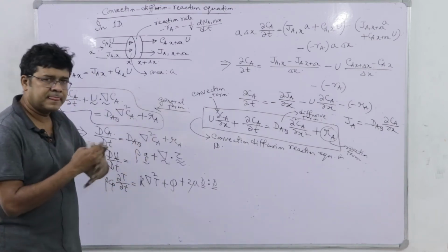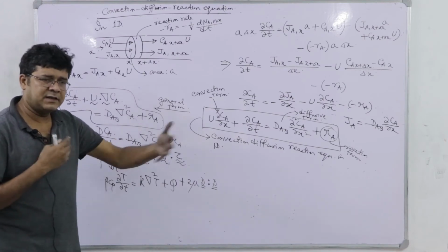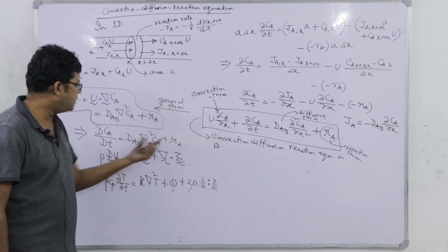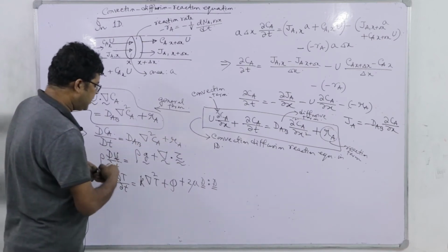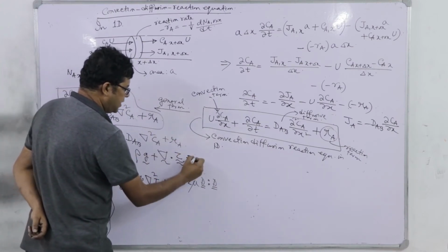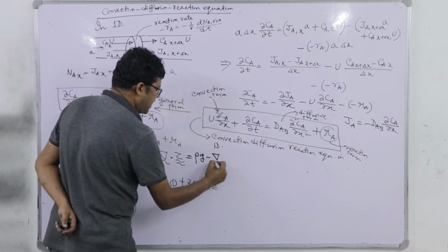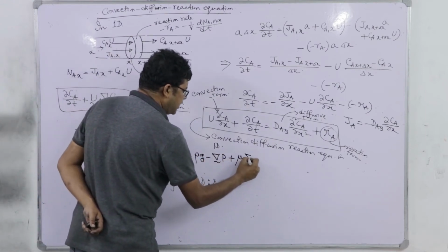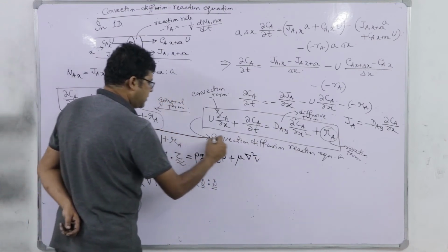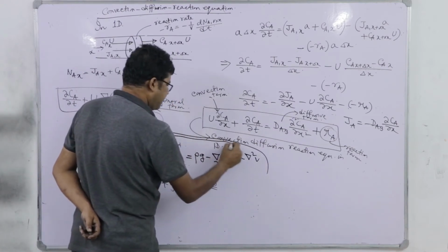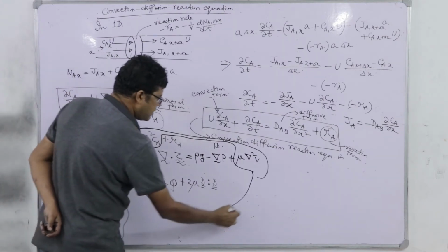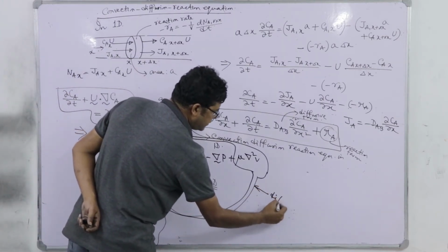And on the right hand side we have either the growth term or the dissipation term, like the diffusion, as it is dissipating the concentration through the molecular diffusion process. So, this is the diffusion term. We can get the diffusion term if I write this for a Newtonian fluid, that is rho g minus grad of P plus mu into grad square V. So, this and this, they are diffusion terms.